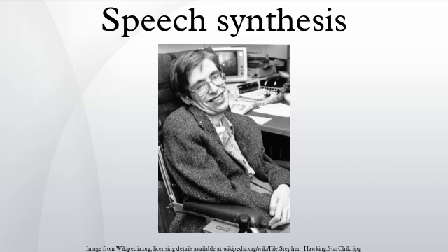One of the related issues is modification of the pitch contour of the sentence, depending upon whether it is an affirmative, interrogative or exclamatory sentence. One of the techniques for pitch modification uses discrete cosine transform in the source domain. Such pitch-synchronous pitch modification techniques need a priori pitch marking of the synthesis speech database using techniques such as epoch extraction using dynamic plosion index applied on the integrated linear prediction residual of the voiced regions of speech.